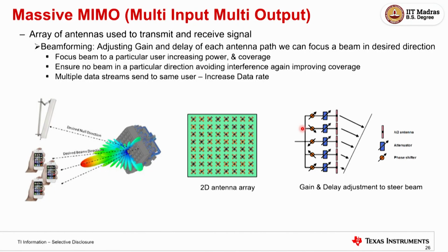This MIMO, what we call multiple input, multiple output beamforming, or they call it an active antenna system, because the antenna is not passive now. You're trying to do this delay and stuff, which is also electronics behind it. This is the key heart of 5G, and that will move over to any technology that comes after this, like 6G. You can see in the picture, I can give a beam specific to a mobile user. That's how I am increasing the coverage, data rate, and all that stuff with the same hardware. And the hardware is that the number of antennas has increased.